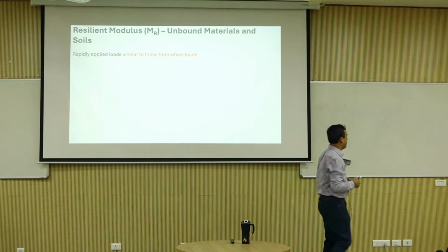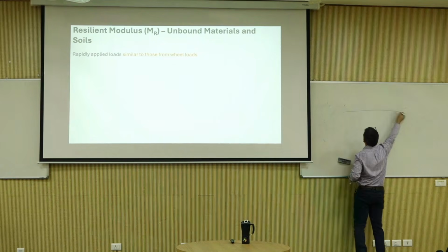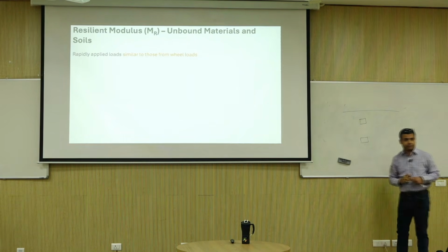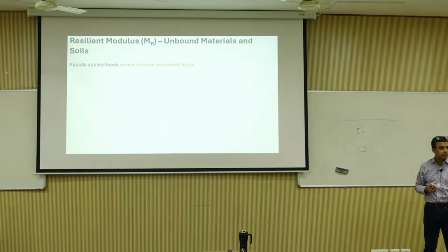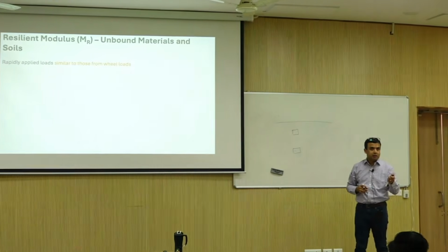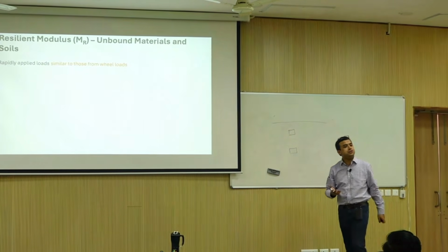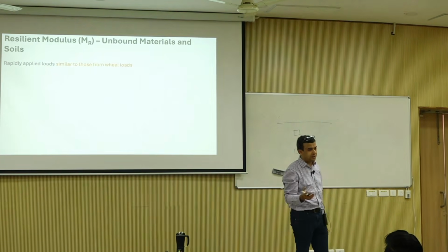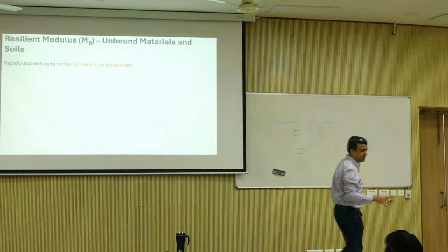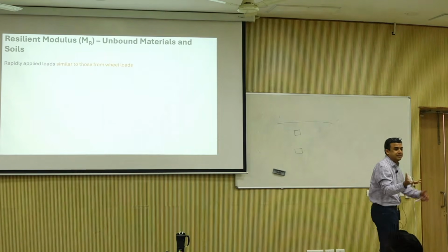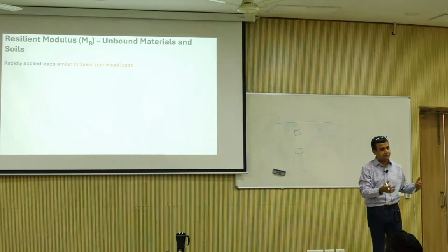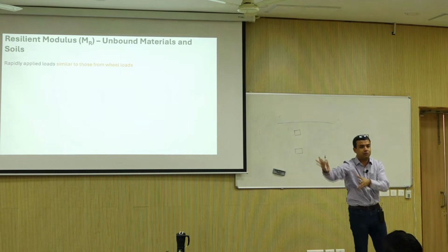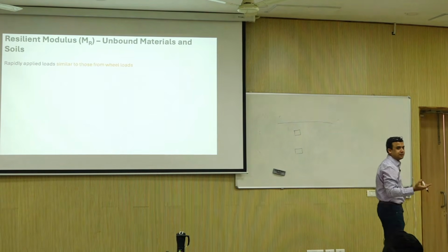Agree? So we are putting on this pavement two pressure sensors, here. It can be pneumatic, it can be piezoelectric, it can be vibrating wire. Vibrating wire does not work very well under dynamic loading, but yeah, it can be anything. Technology does not matter. It can be servo hydraulic. You can have an air based system where, as the load goes, air gets pumped out to something. Anything. Sensors are sensors, right?